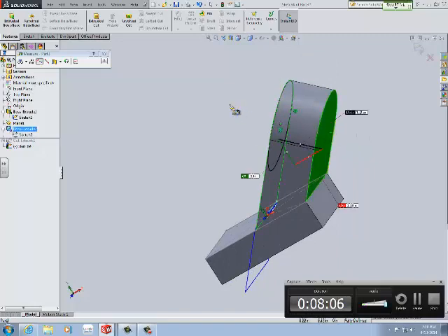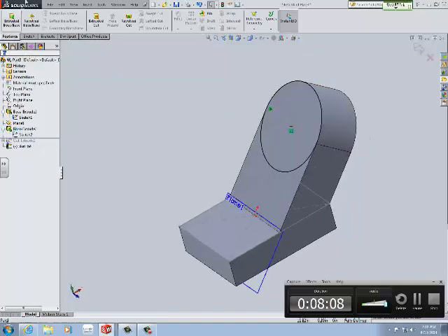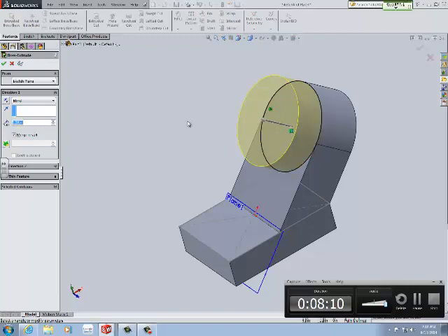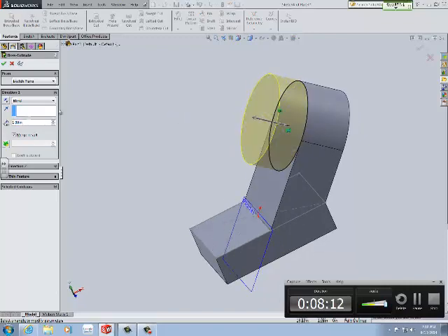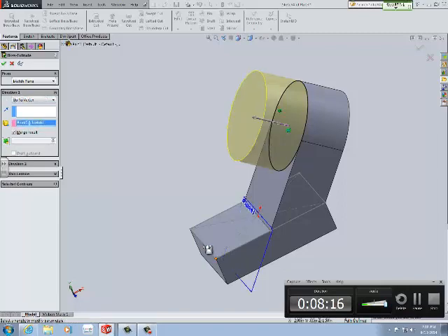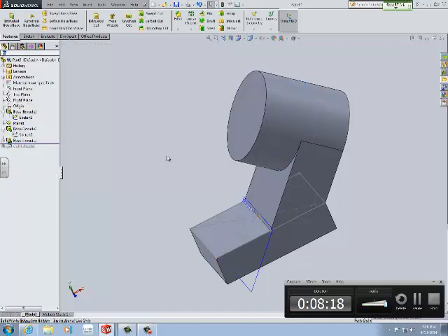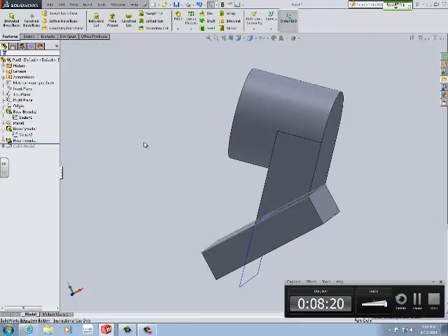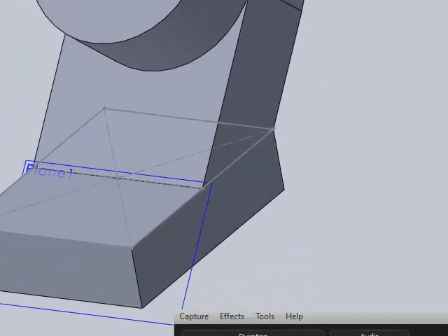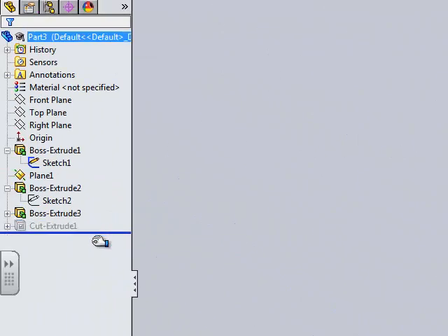relationship. So you can see this one's already defined. Oh, it's even with this, so we can do a vertex again. That definition goes right up to the vertex, we go up to this here. Next we just need dimensions, so that it extrudes up to that vertex, creating that shape. Now we can move this 26. We'll activate it, but that defines our sketch.